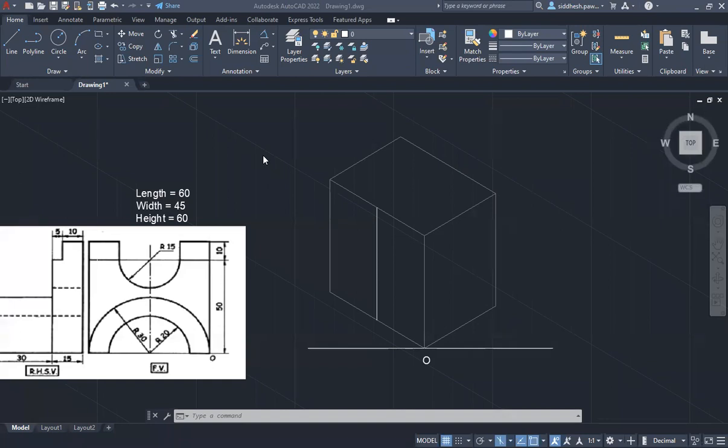Sir, how did you draw the center line? You press F3 and then it will automatically show you the midpoint. Vinay, you press F3 and then when you take the line command, it will automatically show you the midpoint.